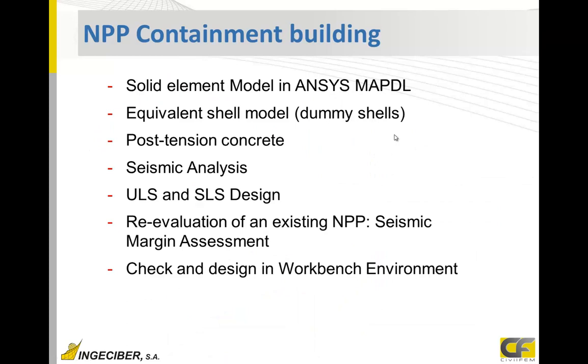Well, as I said, in this nuclear power plant, in a solid element model in ANSYS, CivilFEM is going to generate an equivalent shell model for integrating stresses from solid elements and obtaining forces and moments. So we will be able to have, in a solid element model in ANSYS, stresses and all solid element results plus forces and moments in a dummy shell model. We are going to apply post-tension stress on concrete with tendons, seismic analysis, ULS and SLS design, and seismic reevaluation.